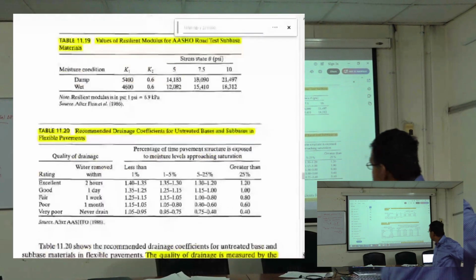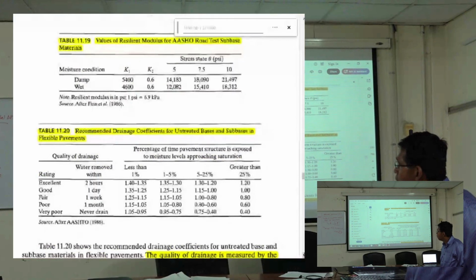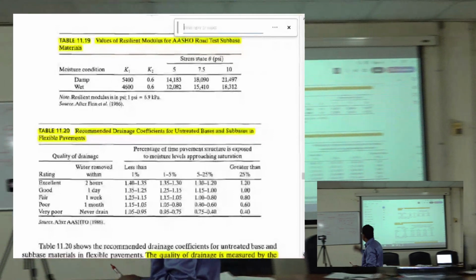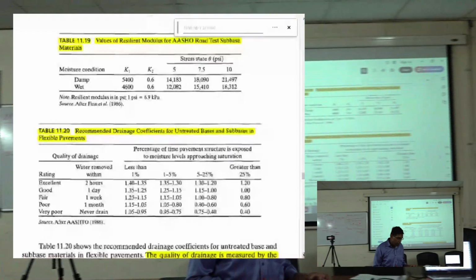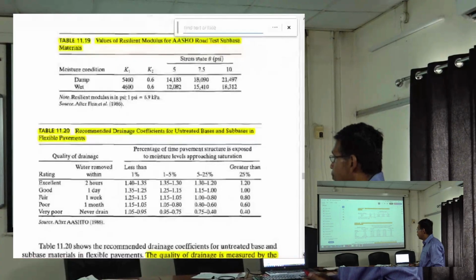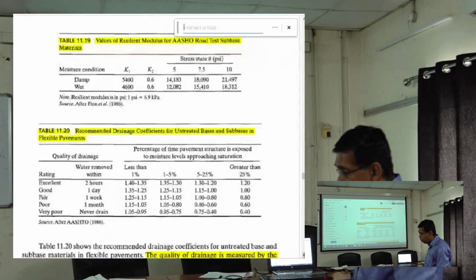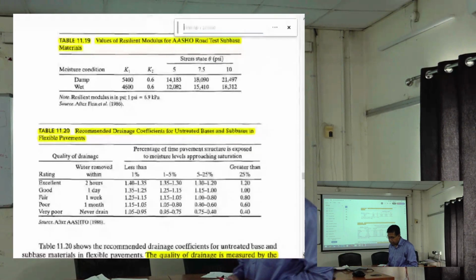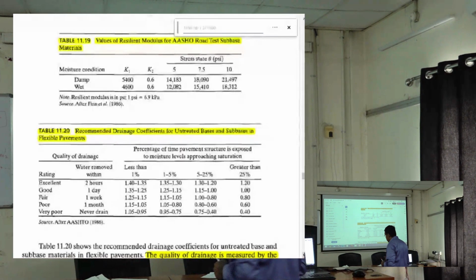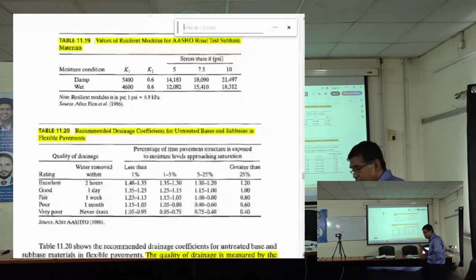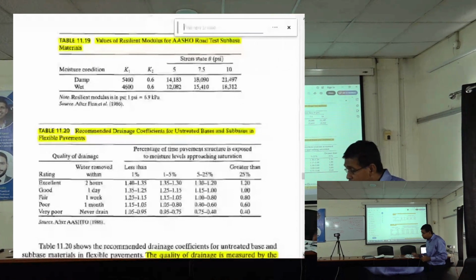So how can this serviceability loss due to environment be considered in Indian conditions? Yeah, absolutely it can be considered. You should be able to look at loss of serviceability due to frost heave in this region. Absolutely. So you have freeze-thaw happening all the time. Frost heave is a serious concern in the northern region. So yes, it can absolutely be considered. It's just that how you quantify it is a challenge, right?